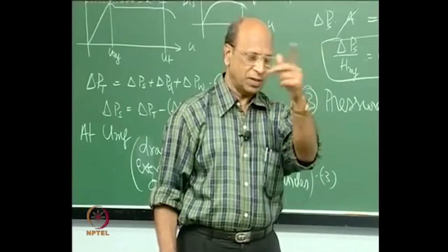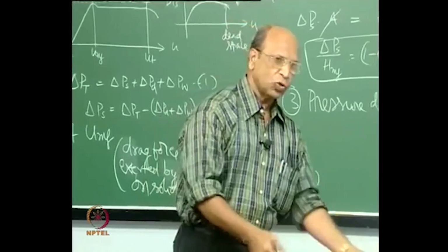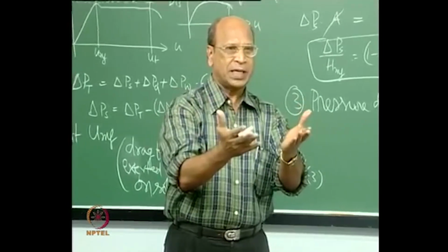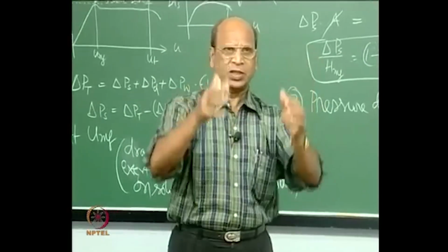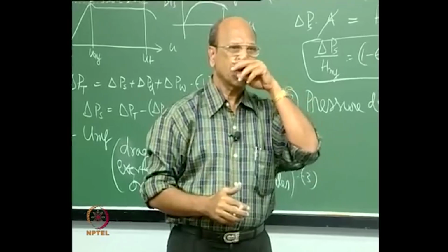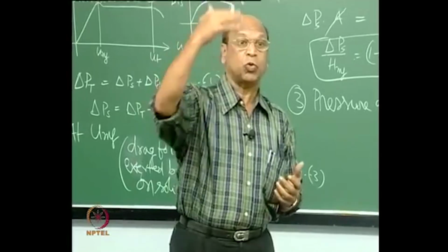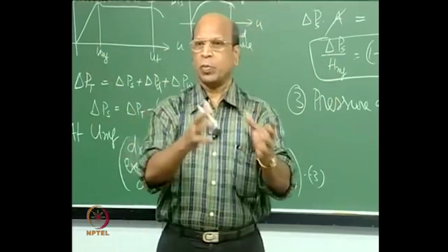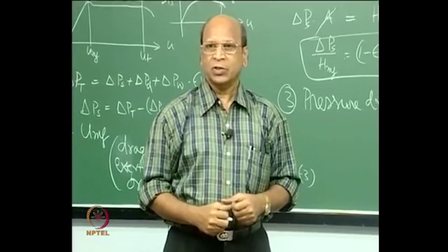Interaction I have seen, I have not used for distillation, for some other column, a turbulent bed contactor, I have used, and I also used perforated plates, and then when liquid is coming from the top and under some conditions the entire liquid will be moving like this inside the bed. Our diameter was 10 inches, a slightly bigger column. Okay? Now, if you imagine this kind of movement in the industry where they have 2 meters diameter, it will have tremendous pressure. The entire column also may be moving this way, that way, if you are not properly supporting it. Okay. So, that is because of the interaction between these bubbles and liquid.